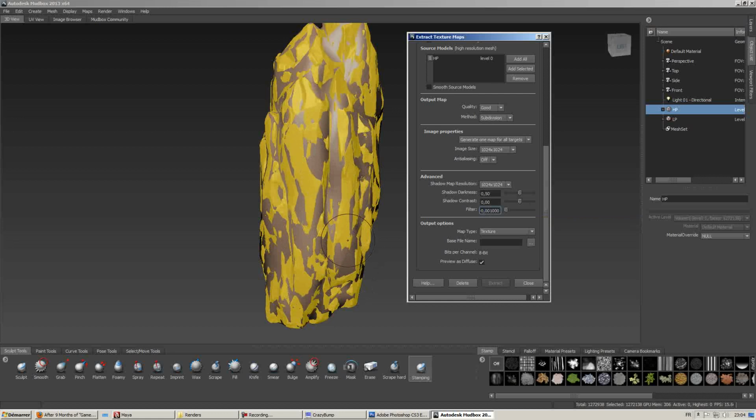So you'll end up with a black and white texture map. You're gonna get pure black and pure white values, you're not gonna have any gray values in this texture map. So it's really useful if you use it as a layer in Photoshop, as a linear add layer to highlight the edges on your color map.